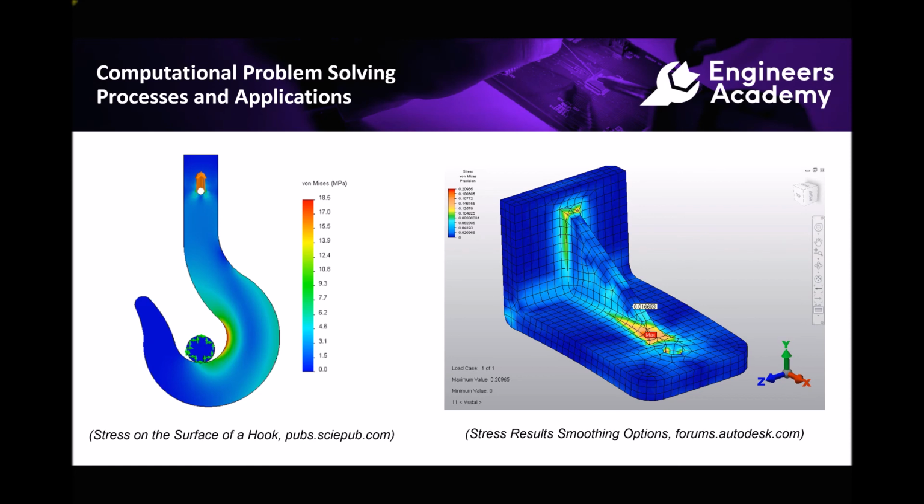And what the software does is it assigns arbitrary values to each of these nodal points. And then what it does is it looks for solutions. It's kind of a trial and error process. So when we talk about the first iteration, it is going to be very inaccurate because arbitrary values are assigned to each of these nodal points, and then the computer software checks to see if those values that it assigned were correct. Obviously in the first iteration this wouldn't be the case, so it moves on to the second iteration and it makes a second approximation, and this approximation is going to be more accurate than the first because it already has some information about those systems of equations.